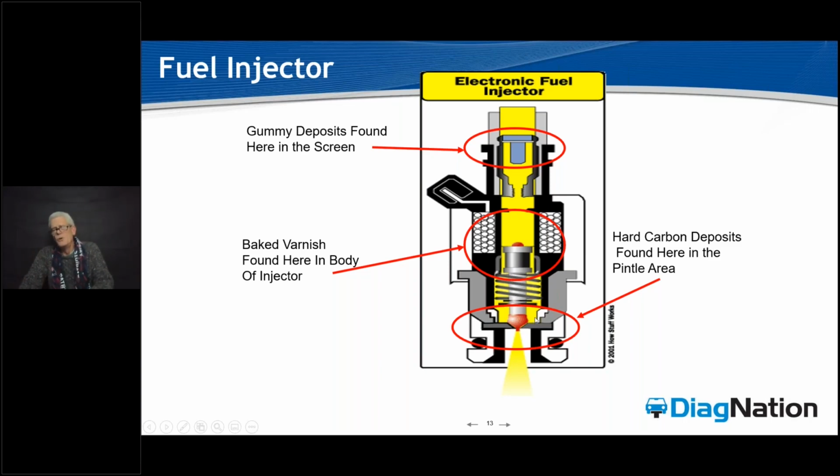Now, to move down here, when we talk about GDI going directly into the combustion chamber, this is where we get real quick drivability fouling on short trip cars that are building carbon quickly. And that's because as this tip falls down here, okay, and the fuel gets restricted, most of our GDI injectors will either have 2, 5, or 8 injection holes, depending on whether it's spray guided or spray directed engine, or simply just a Bosch system, okay? Either way, those are going to be very seriously sensitive fine tolerance injectors.